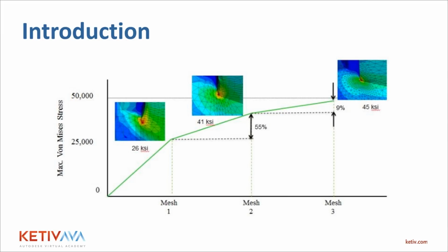You can control the mesh to lead to convergence by reducing the element size and, in conjunction, monitoring the changes in the results. Now, models with certain complex elements tend to converge with smaller element count than others, but the time and resources associated with these complex problems may sometimes be prohibitive. So most FEA studies, at the end of the day, require you, the analyst, to strike a fine balance between analysis time, the cost to run the analysis, and the desired accuracy.